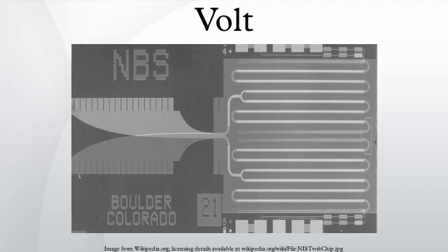Common voltages. Nominal voltages of familiar sources: nerve cell resting potential, around 75 mV; single cell rechargeable NiMH or NiCd battery, 1.2 V; single cell non-rechargeable alkaline battery, 1.5 V; zinc carbon battery, 1.56 V if fresh and unused; LiFePO4 rechargeable battery, 3.3 V; lithium polymer rechargeable battery, 3.75 V; transistor logic CMOS power supply, 5 V; USB, 5 V DC; PP3 battery, 9 V; automobile electrical system, nominal 12 V, about 11.8 V discharged, 12.8 V charged, and 13.8 to 14.4 V while charging.